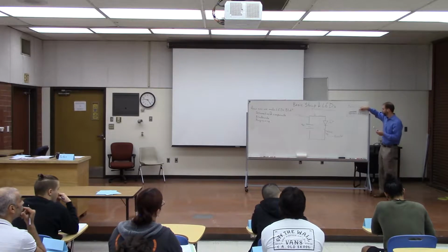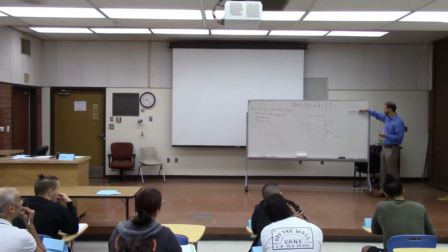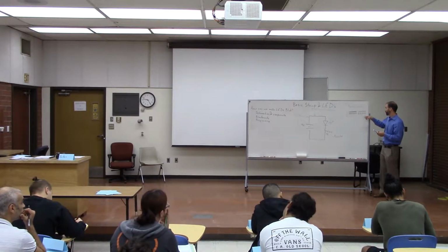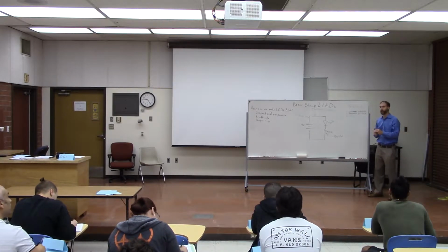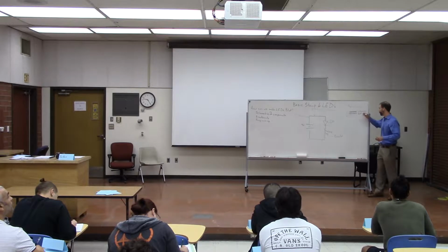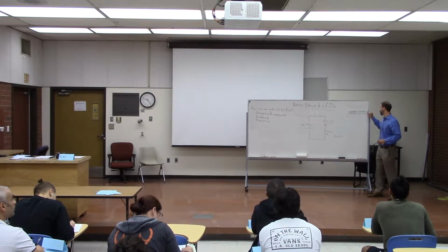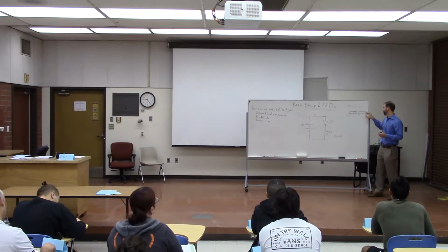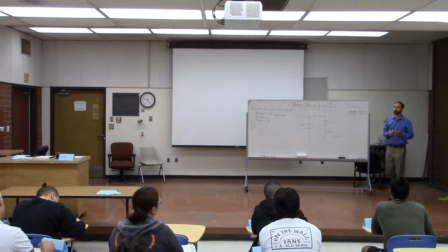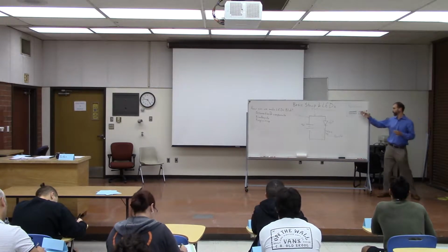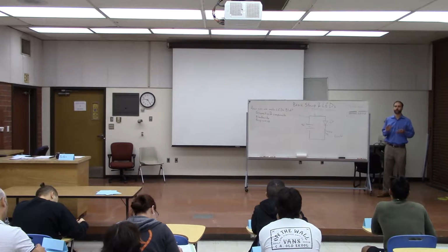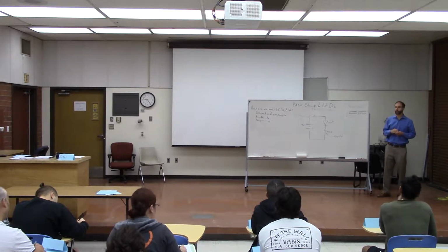And there's no connection across this trough either. So the left side of the board is not connected to the right side of the board. Okay? So this would be like row 20 or something like that. So row 20 is separate from row 1, right? So those two things are not connected to each other. Does that make sense? Okay.